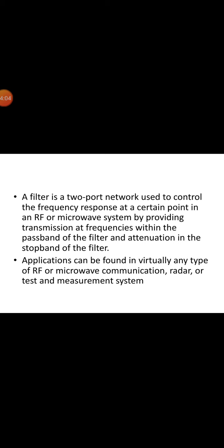Now let us first consider the propagation characteristics of an infinite loaded line. Each unit cell of this line consists of a length d of transmission line with a shunt susceptance across the midpoint of the line, and the susceptance b is normalized to the characteristic impedance. If we consider the infinite line as being composed of a cascade of identical two-port networks, we can relate the voltages and currents on either side of the nth unit using the ABCD matrix.